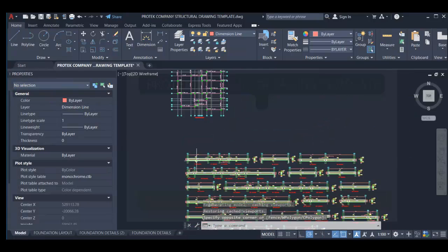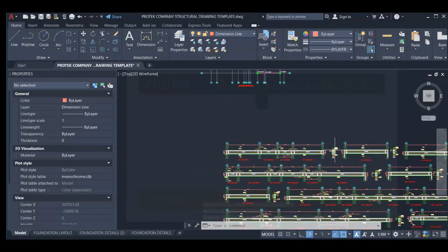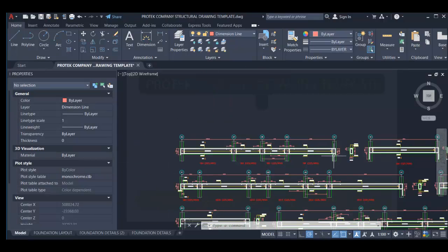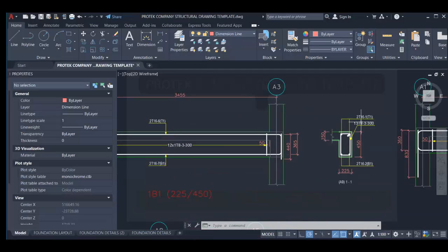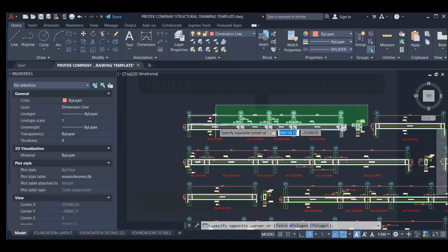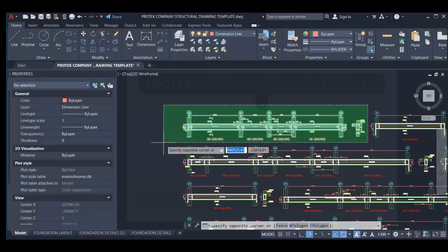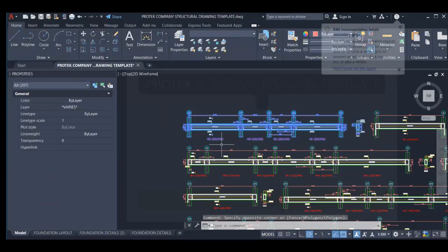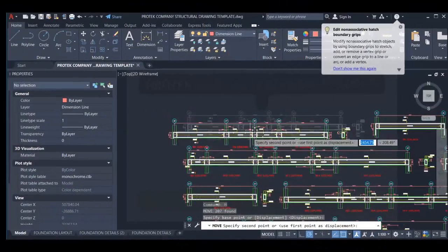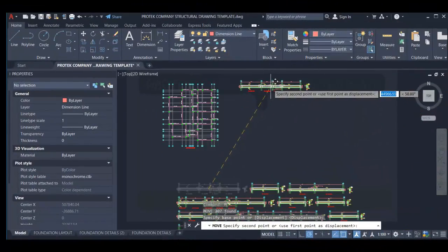So we want to be copying this beam out. We copy this beam including the sections, you can see. So just click over here, and then move your hand over the beam to do a shade like this, then M on the keyboard for move. Enter, pick the beam, move it up here and place it here just like this.